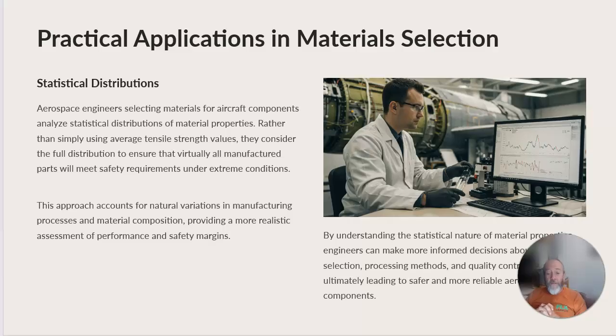And realize that different types of materials have different material properties, but those properties aren't fixed quantities. You can go to a chart and look up what the tensile strength of a specific metal is. The reality is that that is not a fixed number. It's a distribution. That is typically the mean of the distribution. So there's a little bit more complexity. And as you get into more complex types of systems, multiple things have to interact, each with its own probability. So much more complex than just what most people realize. You do. You're watching this.